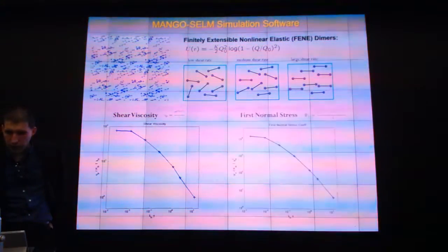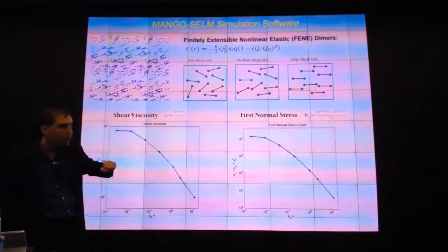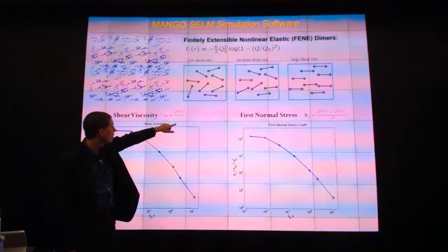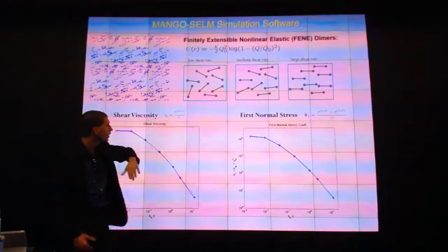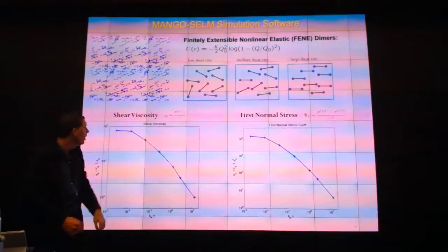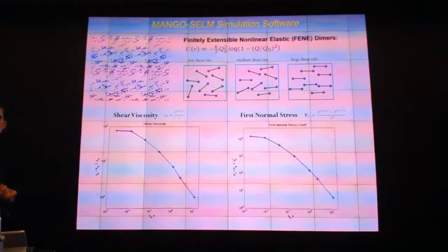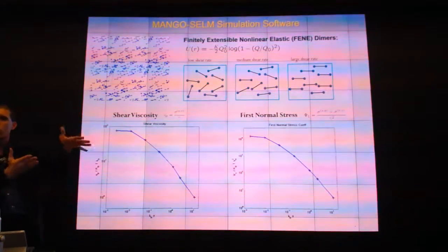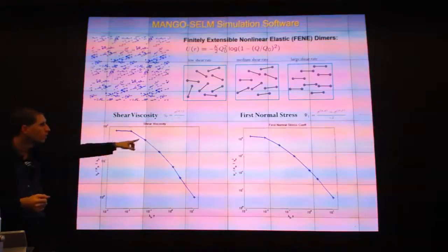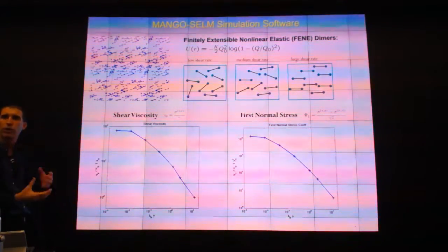So now you can look at, using that stress estimator that I showed you in the previous slide, the contribution to the shear viscosity. This would just be reading off the shear component of the stress over the shear rate. And what you notice, quite interestingly, is you get deviation from the Newtonian response, right? In the Newtonian response, the faster you shear, in proportion, the more shear stress you have. So notice I'm normalizing by the shear rate. If this were level, that would be a Newtonian fluid.